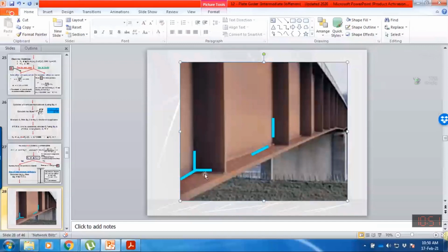So just to avoid this, or just to avoid the stress triaxiality, because this weld is also subjected to the forces developed in this weld, and some forces are also transferred from this weld. It means that any one weld is subjected to three forces, but all the welds are only designed for one force. So how can we avoid this?